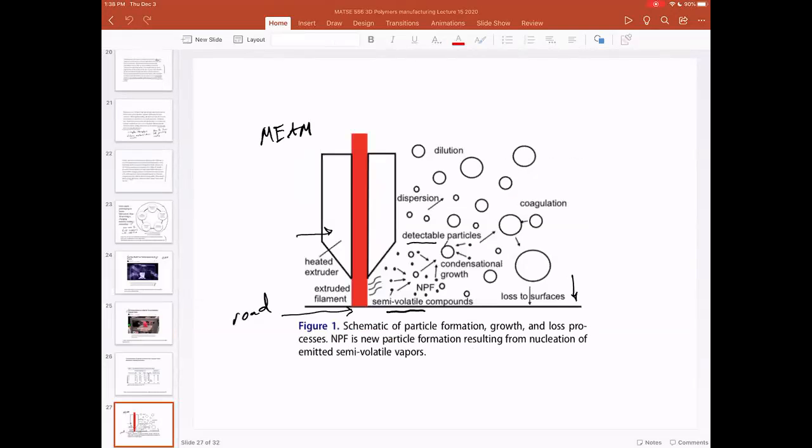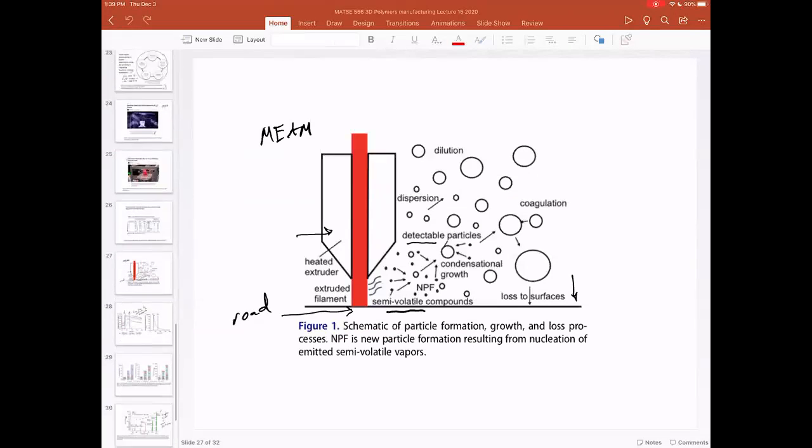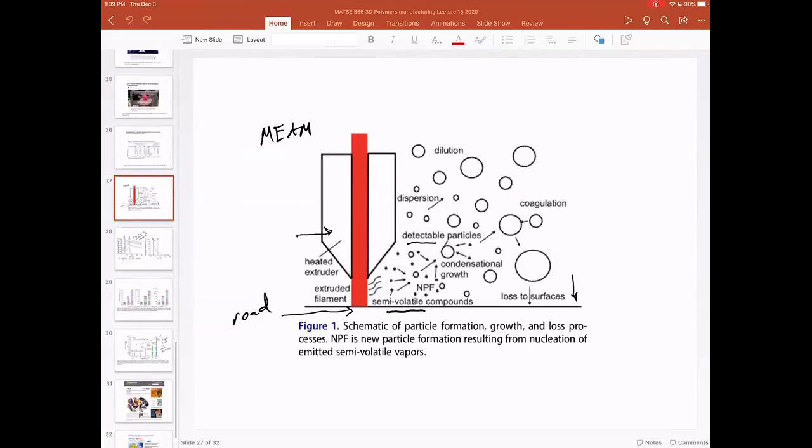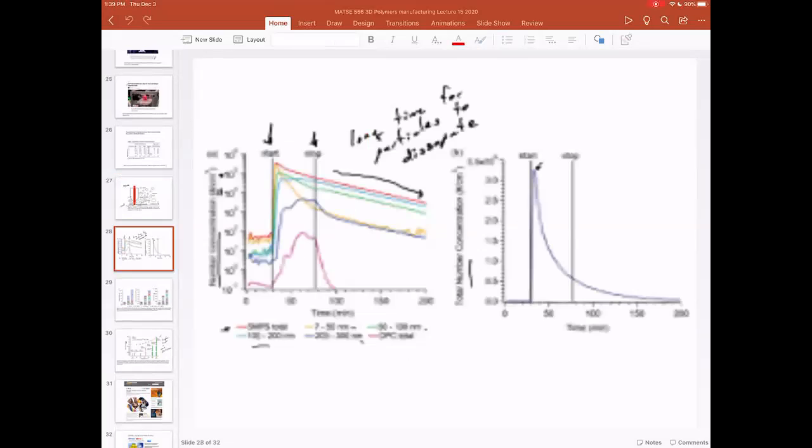And what we learned about was that not only are there the semi-volatile compounds or the fumes per se, the melting plastic that you can smell, but there's a lot of particles that come off of these material extrusion AM printers. And that's because we're shearing a hot polymer through that heated liquefier, and that's going to create atmospheric particles. And those particles are pretty bad for you.